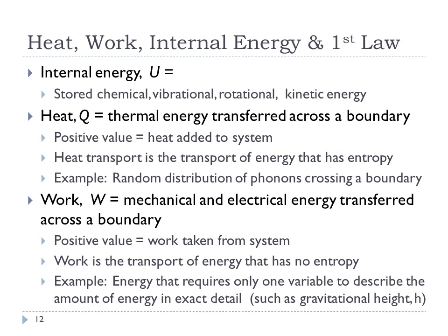So if you could transfer that gravitational energy across a boundary, then we would say that work has transferred into or out of a system. And here we're defining work to be positive if it leaves the system. The reason we're defining it this way is that we have a power plant, and I want the answers to come out positive when we're building power plants. I don't want negative values when we're designing power plants.